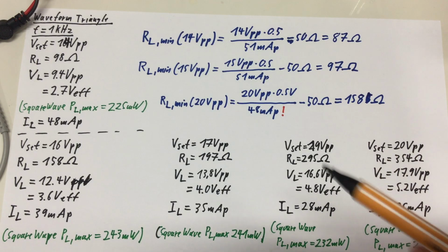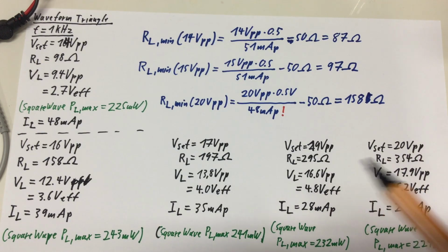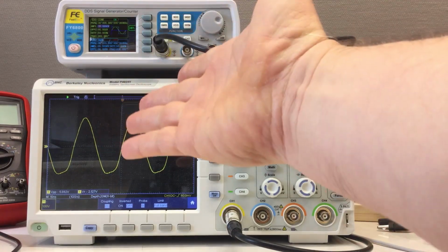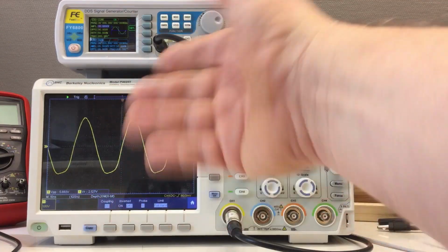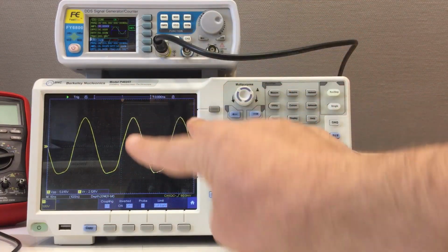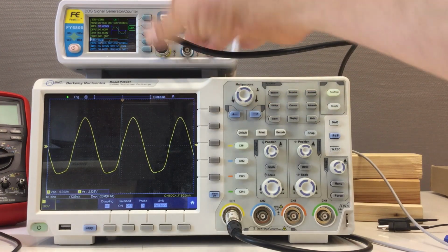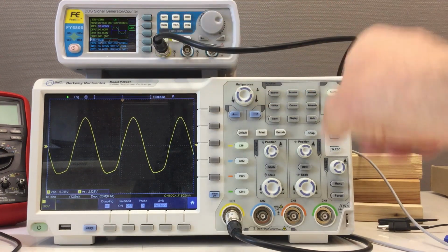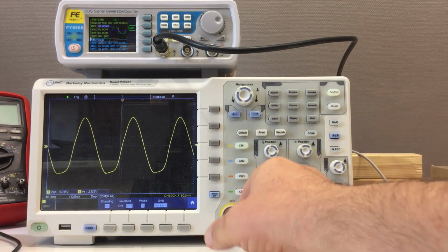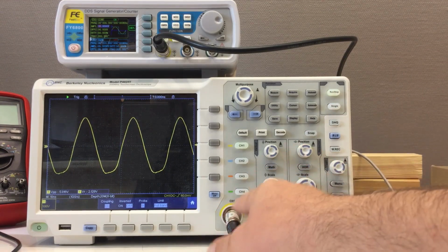Now, what does that mean for high frequency stuff? What does that all mean for high frequency? When you're working with high frequency, you have two options. Either, when you have a 50 ohm impedance source, you use a 50 ohm BNC cable, and at your end you have a 50 ohm terminator.